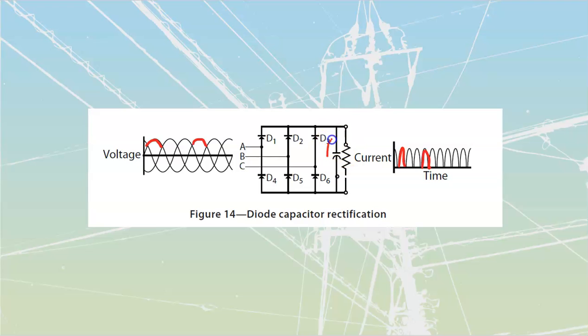And then once we have that cap inside there as well for filtering, then that capacitor is going to carry through some of it. Instead of us having a current rise that's going to look like that, we're going to have a current rise that all of a sudden goes up like that and then back down. It makes sharper edges again. It's not going to be healthy for our system to take lots of pulses. It's obviously going to be far better for this thing to have a smooth amount of current slowly rising in, slowly falling away, rather than this bam, bam, bam, bam, bam sort of sequence that you're going to get off of currents otherwise.